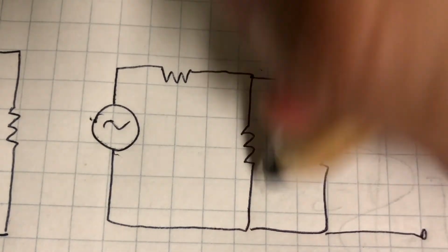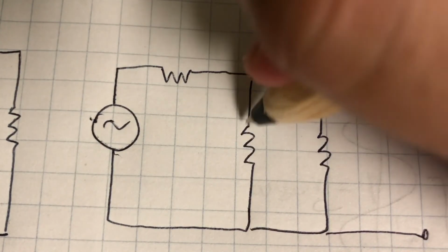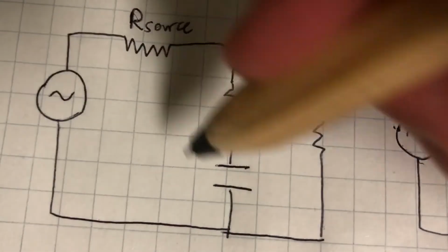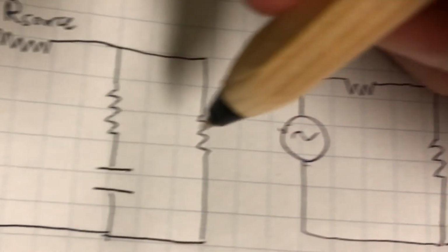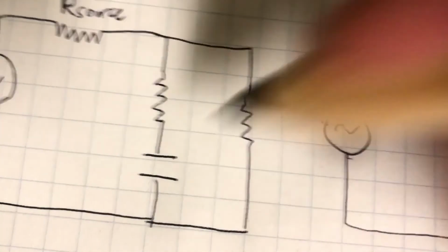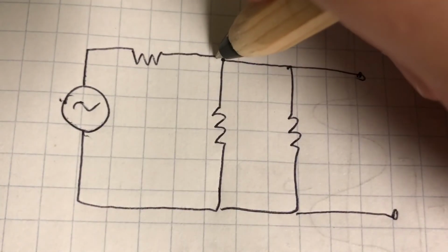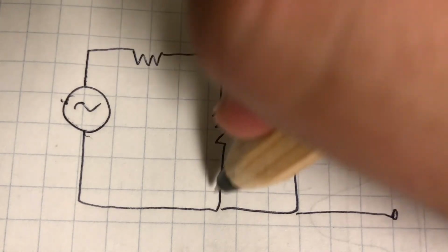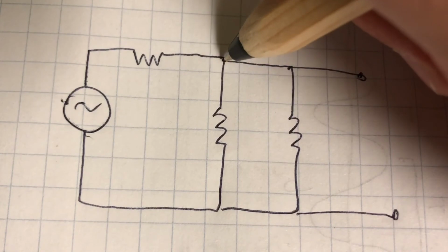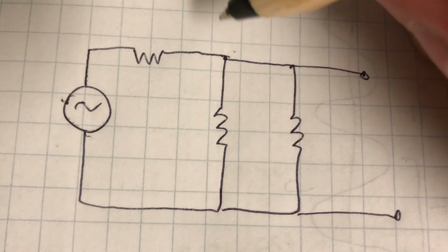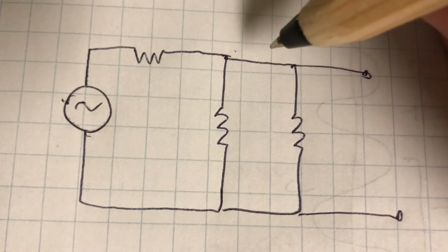And let me explain the middle part right now. So what's basically happening is that over here, the capacitor is being charged up right now, okay? So when a capacitor is being charged up, you can think of it as the current just directly going through it, right? There's very low impedance, and it can just directly flow through it, which means that the current is going to be really high.